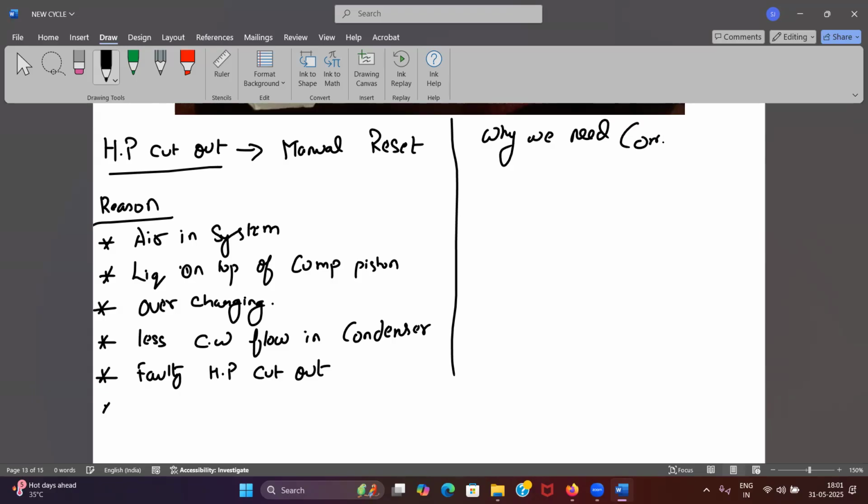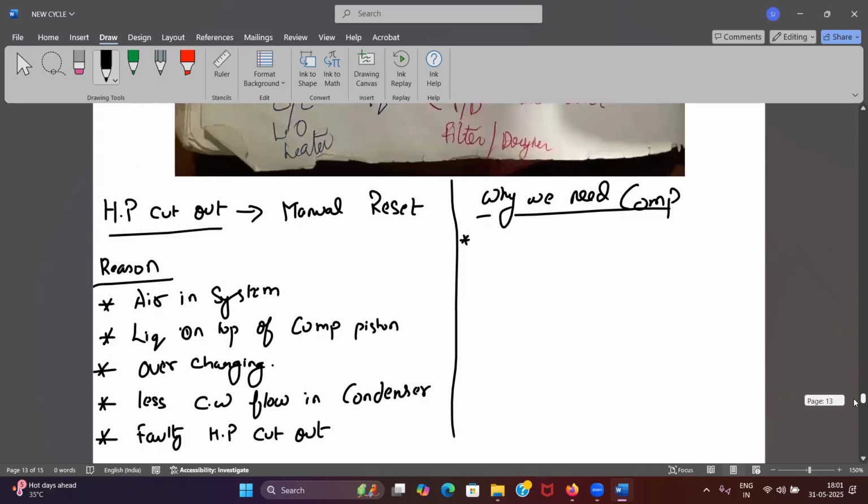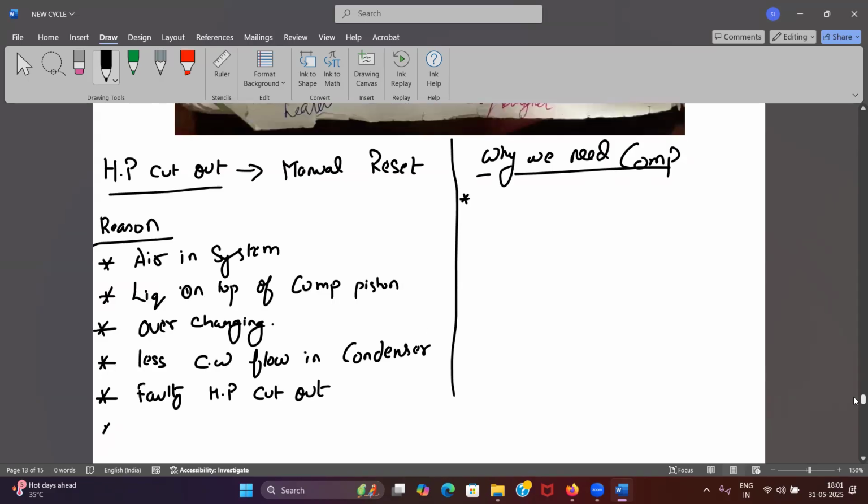Excuse me, sir. Yes, sir, if the oil separator is not draining, that is, if the valve or the drain mechanism is not working, it will keep filling up, and the oil will go to your evaporator coils. It is going to choke the evaporator coils, heat transfer will stop, right? Liquid will be returning back, HP cutout will still take place, okay. Okay, sir.